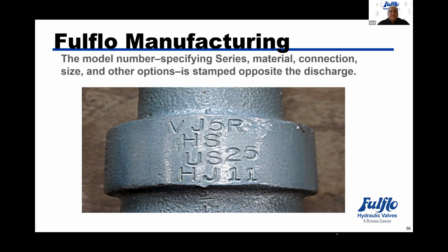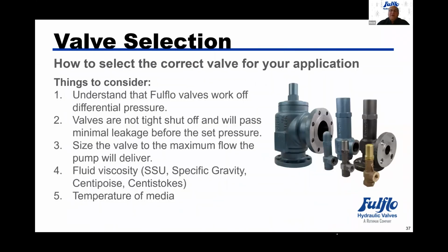Valve selection. How to select the correct valve for your application. Things to consider: understanding that the Fulflo valve works off of differential pressure. So therefore, if there is a back pressure, we need to know what that might be to determine the correct setting at which the valve would operate.